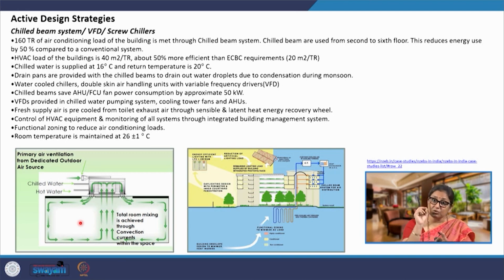But the most interesting part is that this is one building which employs a mixed mode of air conditioning and cooling. During the period when the outdoors are comfortable, the windows are allowed to be opened by the users. The users can open the windows, and the air conditioning system will not be run when the temperatures outside are comfortable. With the windows open, natural ventilation and mechanical ventilation can be turned on.